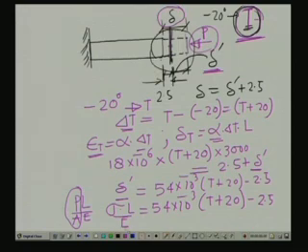Initially, we have allowed the bar to deform in such a way that it undergoes movement freely over that 2.5 millimeter, and then it goes and hits the wall, and then it keeps on increasing because there is a change in the temperature.